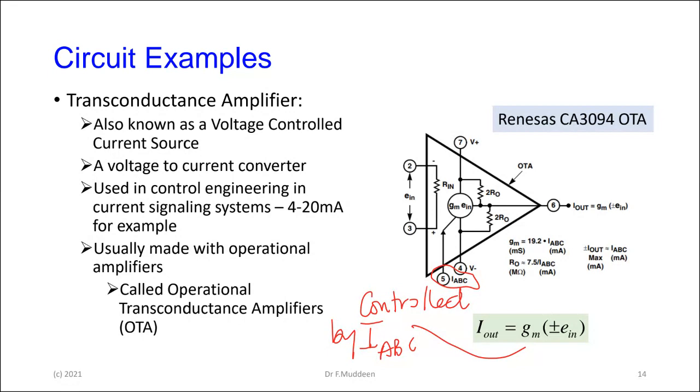Somebody had mentioned this before, and it came up in the lecture with Dr. Radix, for instance, that in a typical process plant, how they send signals from one point of the plant to another is using something called a current loop. They vary the current, and the current goes between a low of 4 and a high of 20 milliamps.